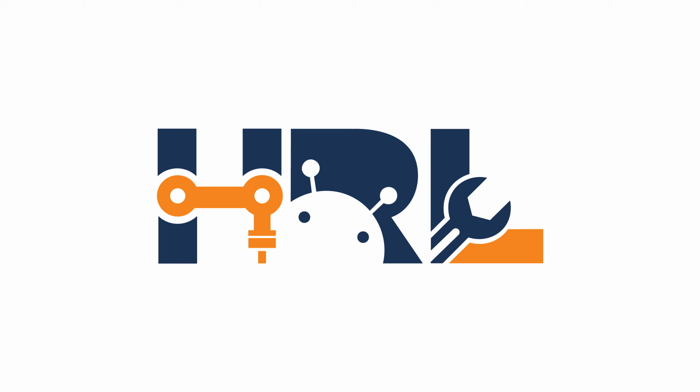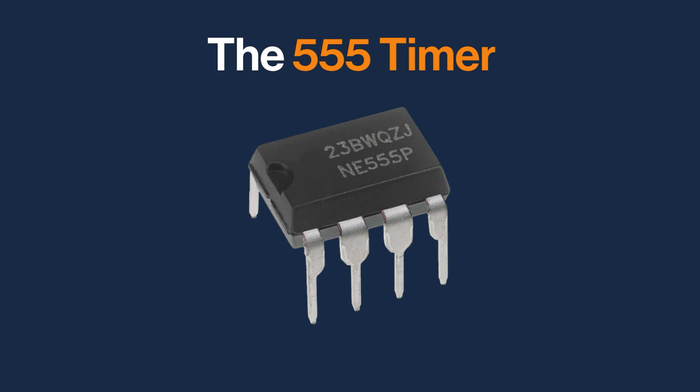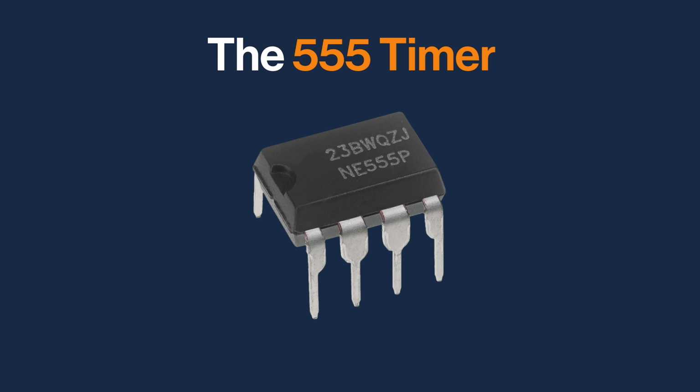Let's break it down. The 555 timer is an 8-pin chip designed to generate precise time delays and oscillators. Inside the chip are things like comparators, a flip-flop, a discharge transistor, and a voltage divider. And all of these parts work together to generate timed pulses, measure delays, and create waveforms like square waves for blinking lights or tone generators.